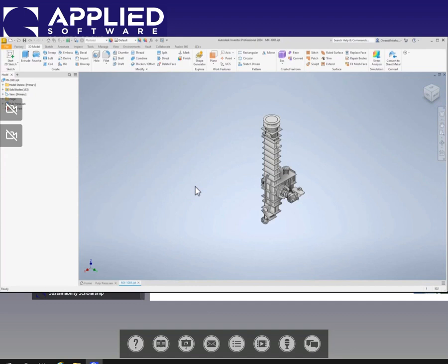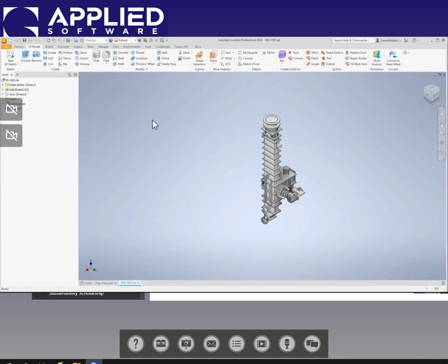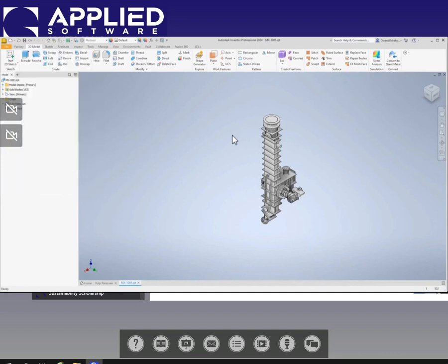This is still an IPT file, and in many instances to work with Plant 3D, you're going to want to export this as a DWG file. So you can do that up here from the Save As, and again, it's cutting that off. But you can do a Save As or export to a different CAD format. So export it to DWG. That is a step in the process that you'll want to do.